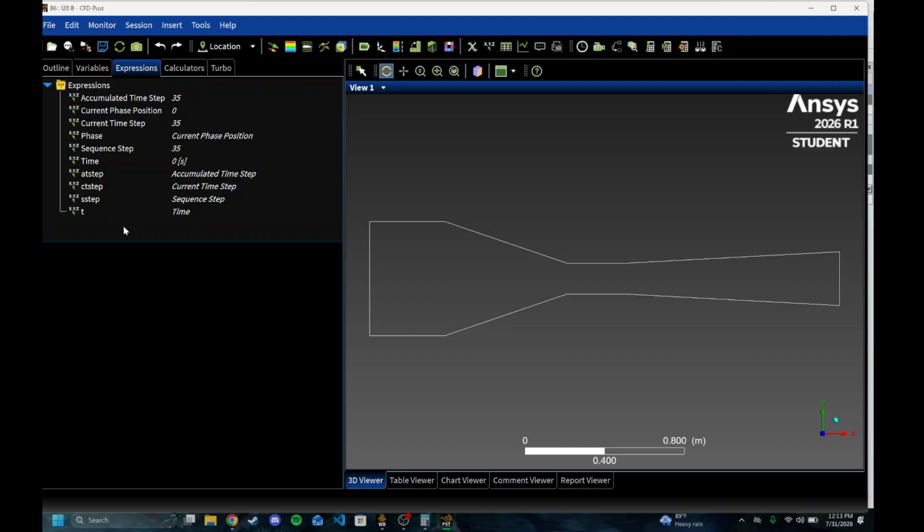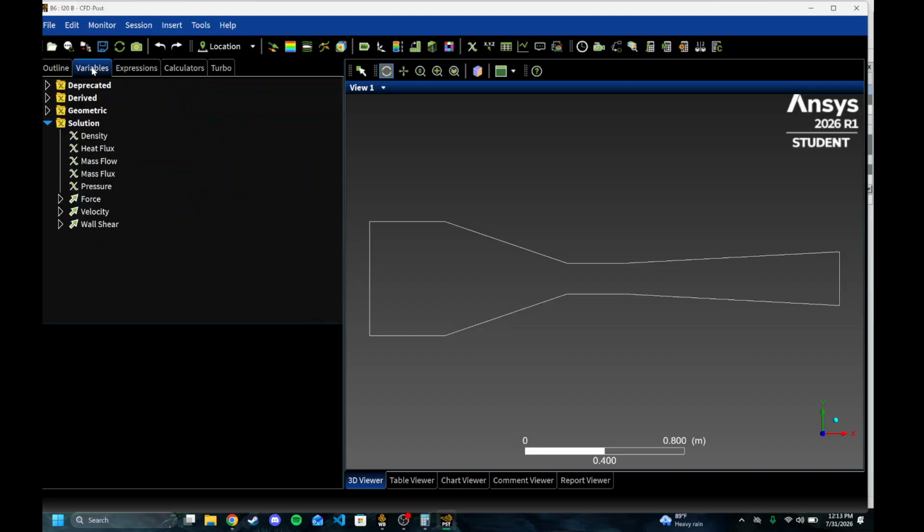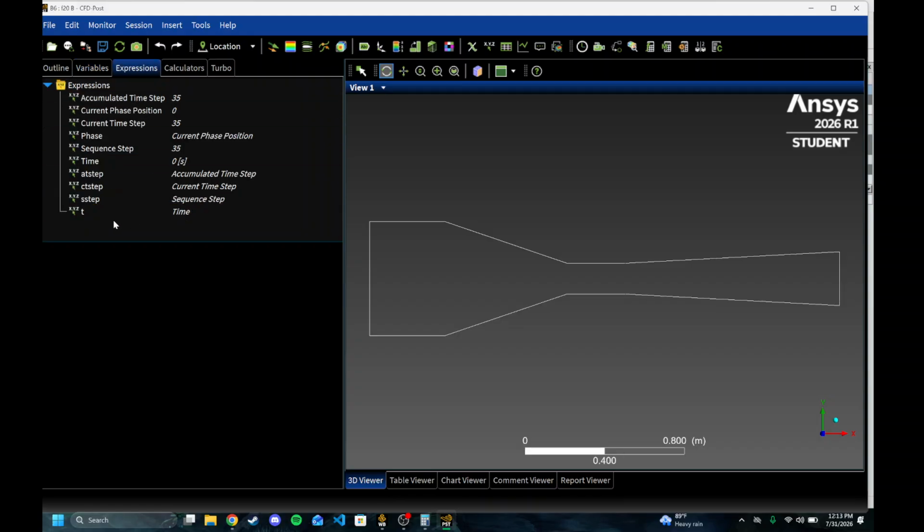So we have to provide contours for velocity, static pressure, total pressure, and dynamic pressure. Now, by default, Fluent includes, of course, velocity and static pressure, which is just the typical pressure variable, right here. This is our static or gauge pressure. So we have to input the dynamic pressure and the total pressure separately. We can do that pretty simply here under expressions.